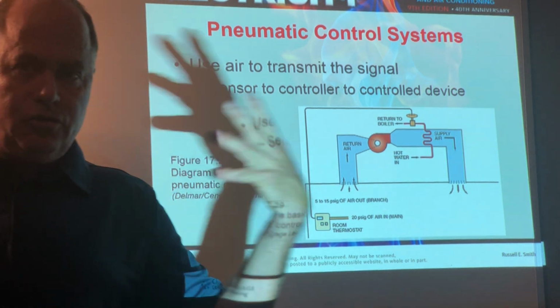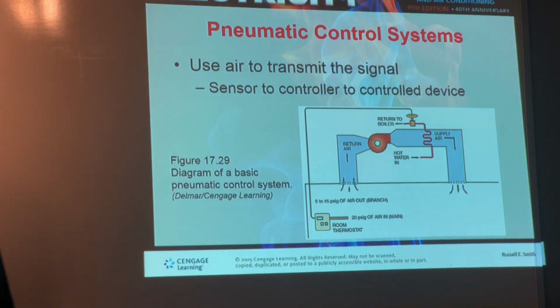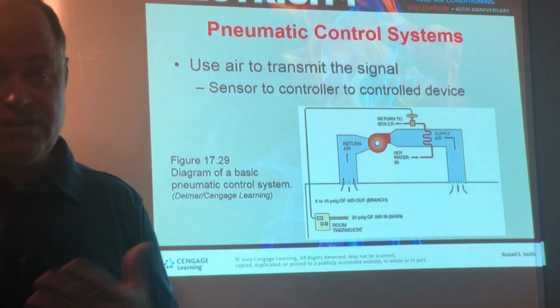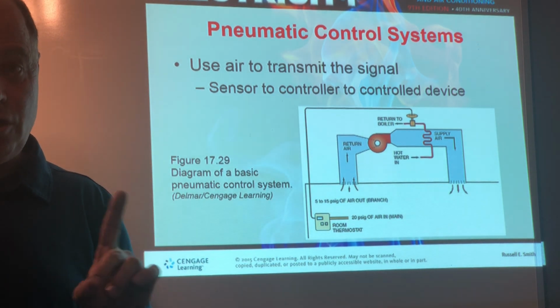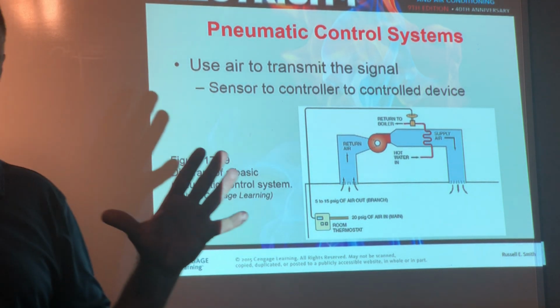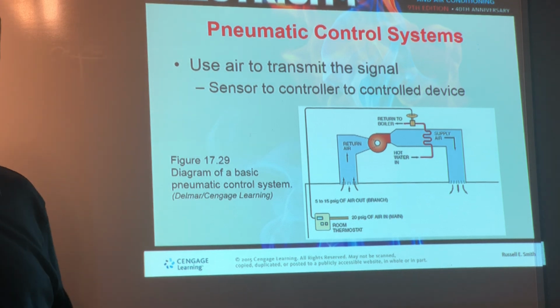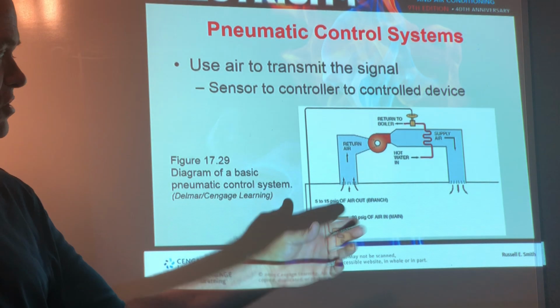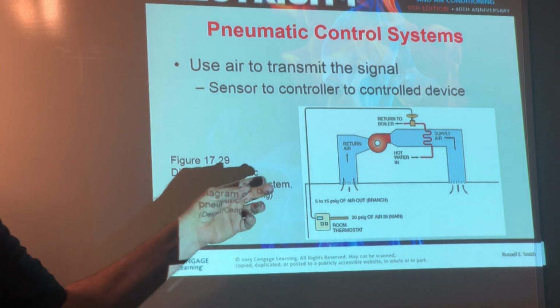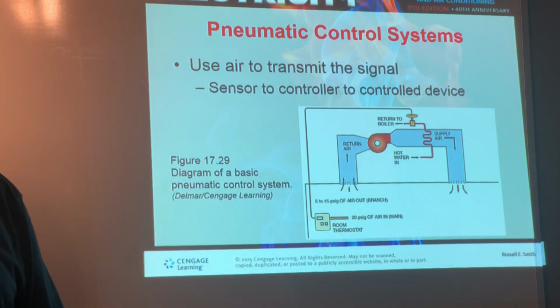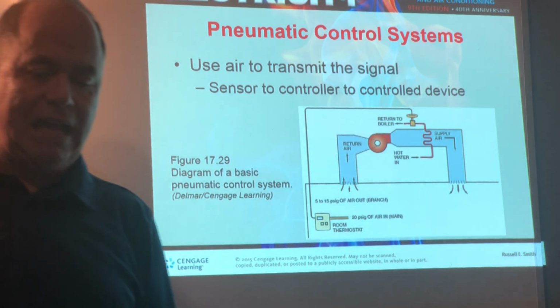Also, as the country grew and high-rises were built, Grandpa helped build the Empire State Building, people worried about fires. And electricity back then, plastic, no. Cloth wires. So, fires, high-rises, let's use pneumatics, right? There are a lot of benefits to pneumatics, and I still like them a lot because I think they're a lot less expensive and reliable than some of these digital motors that we use for dampers and valves. But we're going all digital now, and hopefully over the years they'll come down in price more and be a little bit more reliable and last more years than what I've seen them lasting.